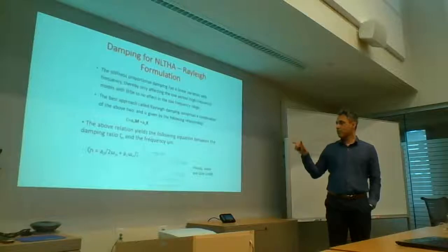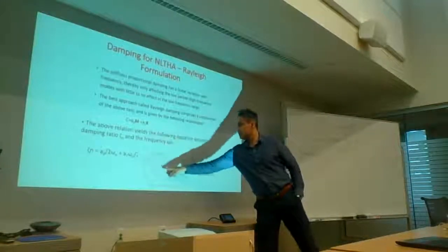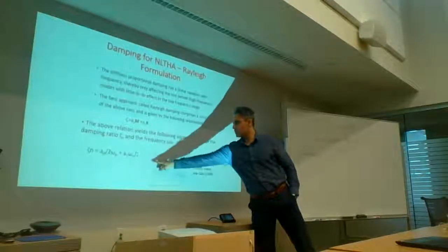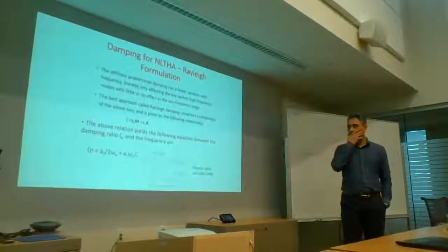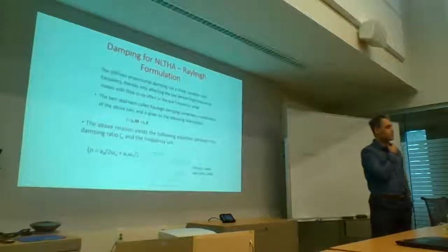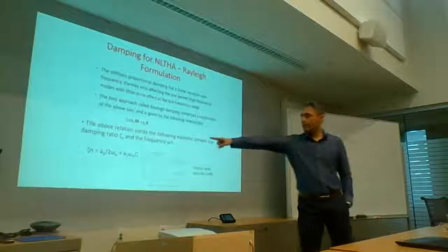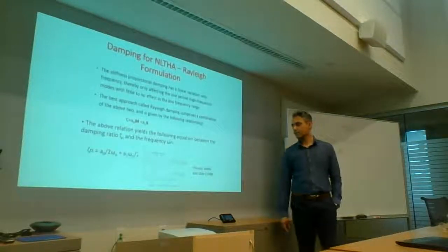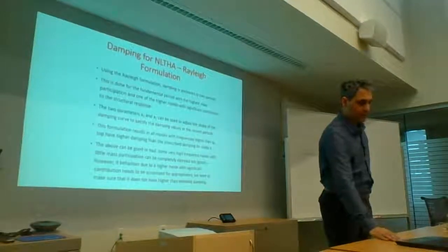So when you add the two together, you get this Rayleigh curve, which looks like this convex line. And that's what traditionally we use in time history analysis to model damping. So your damping coefficient comes out of that expression, a0 over 2 omega n plus a1 omega n over 2. That's your nth coefficient.